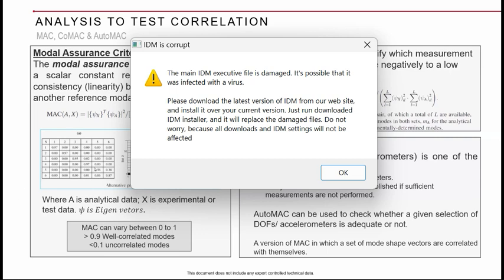But is it really required to worry about all the modes? May not be. Our major focus will be on the first few critical modes, majorly the fundamental modes, and whatever modes are severe from the analysis and whatever modes were dwelled in the testing. Okay, with those responses, because these are coming from the testing and we might have dwelled them or we may have just swept them. And from the sweep data, if the response is significantly high for certain modes, all those modes should correlate in the analysis is our target.